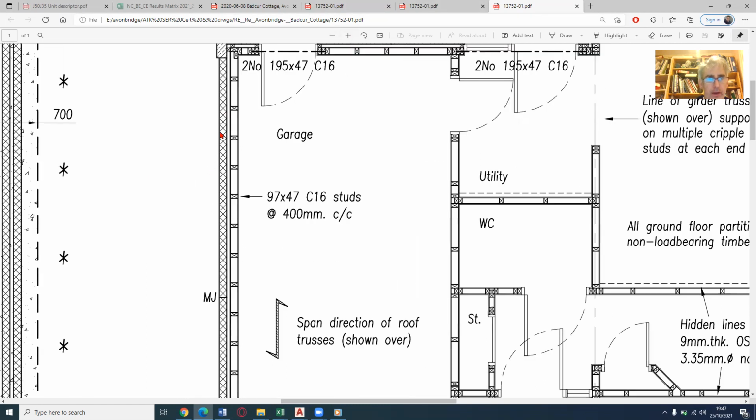It's not bearing down on the masonry. The masonry is there as a kind of a rain screen, but it's not necessarily structural. Okay. The masonry is tied back to the frame, so it does help in some way, but the main weight or the main loads are transferred through this frame.